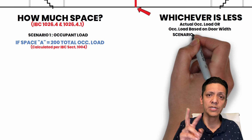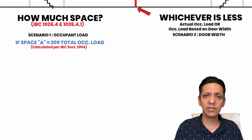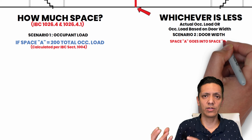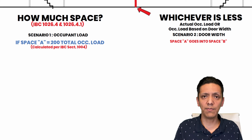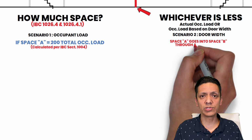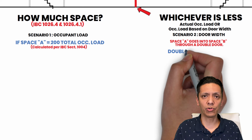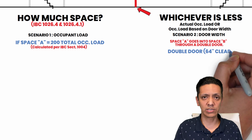And option 2 or scenario 2 is taking into account the door width that goes from space A into space B. For example, if space A exited into space B using a double door, that just for the sake of an example here, let's assume that the double door has a clear width of 64 inches.